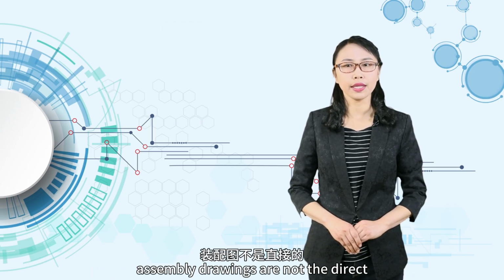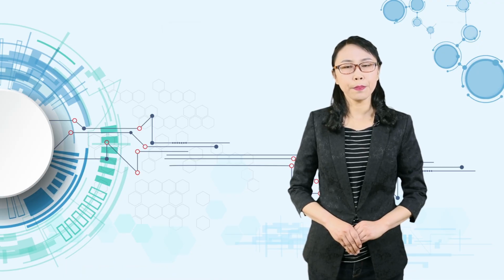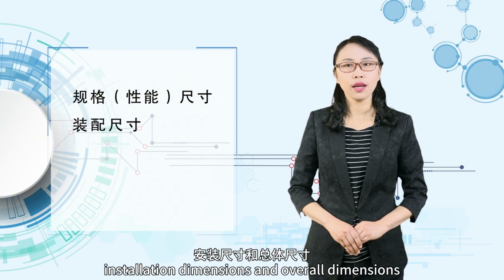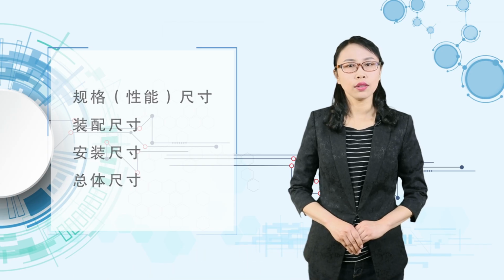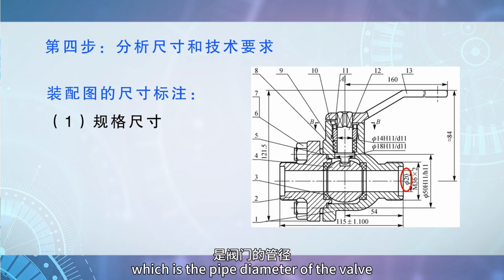Assembly drawings are not the direct basis for manufacturing parts, so only some necessary dimensions need to be labeled, including specification and performance dimensions, assembly dimensions, installation dimensions, and overall dimensions. So, the specification dimension of the ball valve is phi 20, which is the pipe diameter of the valve.